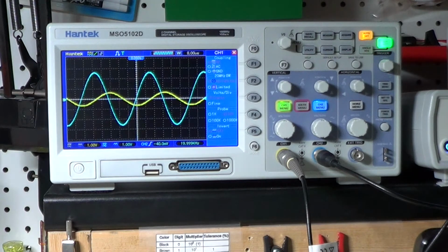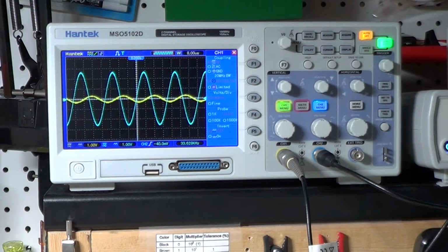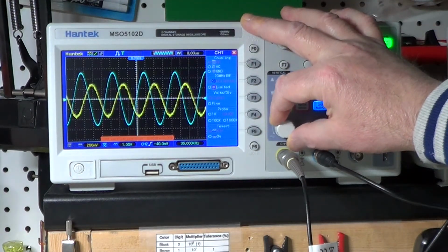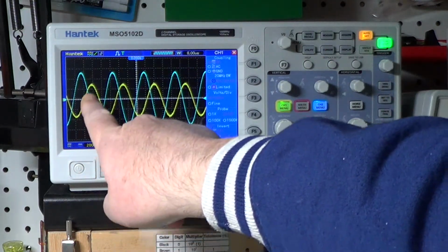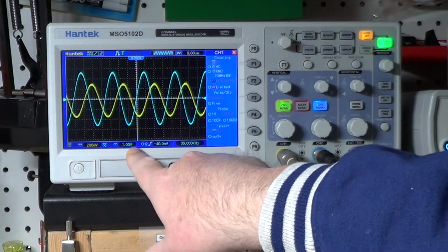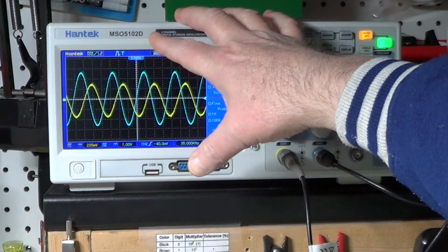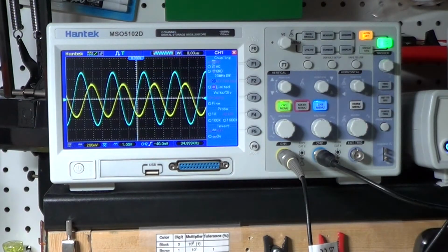This means that we have already exceeded the cutoff frequency, and so now we are purely in the part of the filter where the slope starts decreasing steadily and faster. Look what happened at 35 kHz. Let me increase the scale of the yellow signal so you can better estimate how the phase shift changes. So this is 200 millivolt for the output, while the input is about 1 volt per division. So the input is basically 5 volts, while the output is about 650 millivolts.